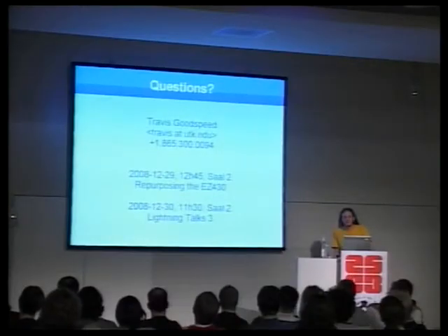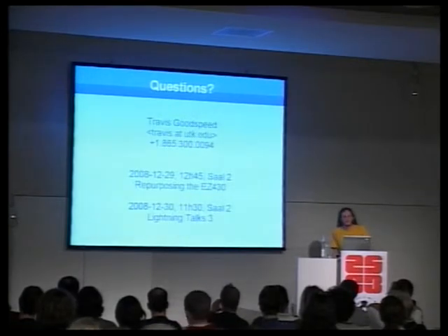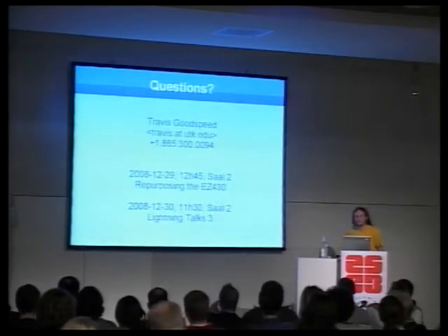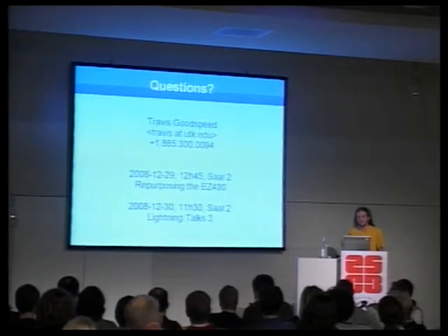Well, I haven't found many devices which do have the JTAG fuse cut. Most devices actually leave it open. And it makes sense from a manufacturing standpoint, because if you mess up a manufacturing run and you need to fix things, the JTAG fuse is just in the way.